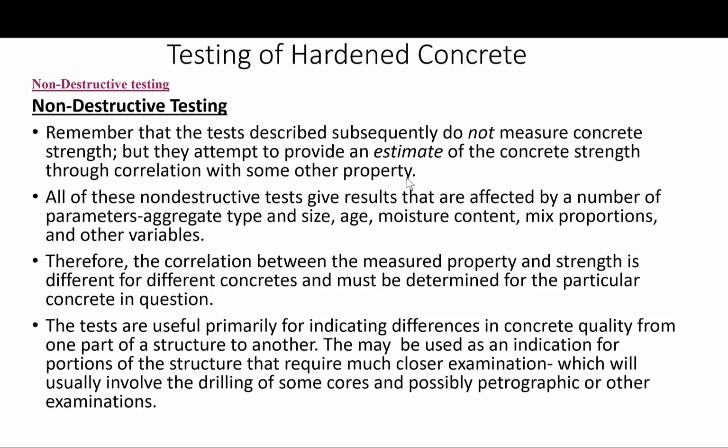However, it must be remembered that the tests described subsequently here do not measure the concrete strength. Rather, they attempt to provide an estimate of the concrete strength through correlation with some other property. All right, again, you have to understand that. Unfortunately, as is usually the case in concrete testing, all of these non-destructive tests give results that are affected by a number of parameters, such as aggregate type and size, age, moisture content, mix proportions, and other variables. So again, we have to be aware of that.